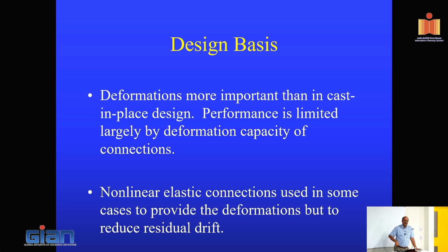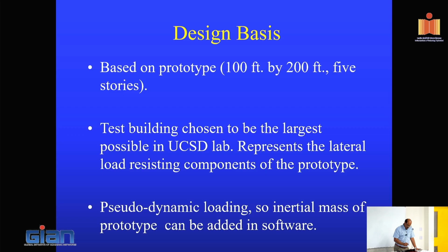So the performance of the precast system is now tied to the deformation capacity. You have to have the deformation capacity, which should in turn open up the gaps, or the deformation, at the joint. The non-elastic connection can be used to increase damping, which I'll talk more about maybe next week as well.